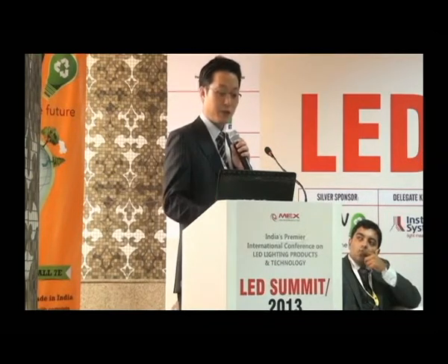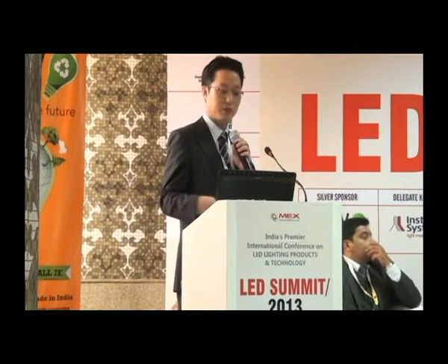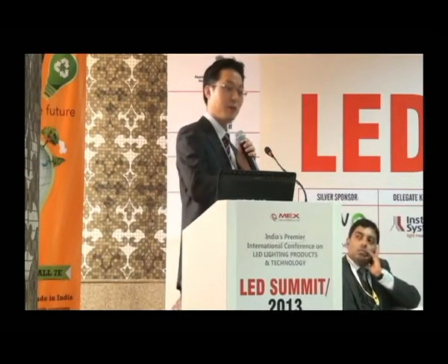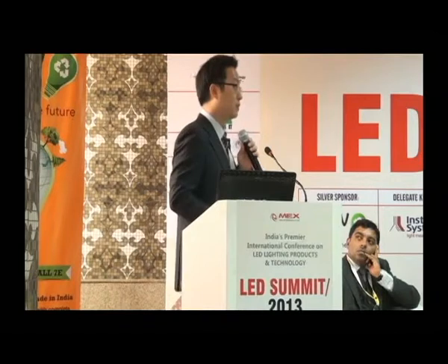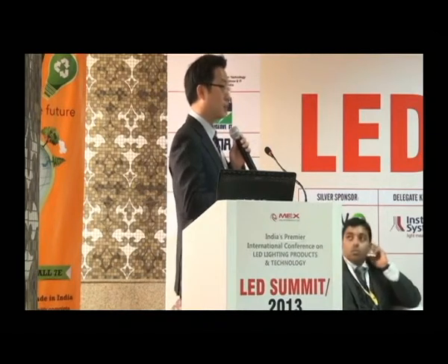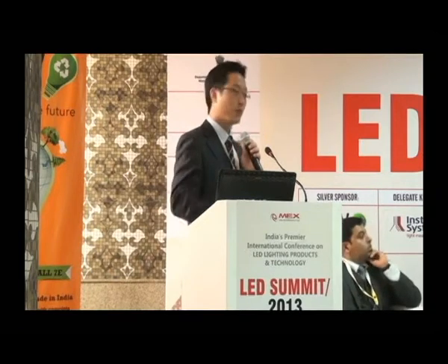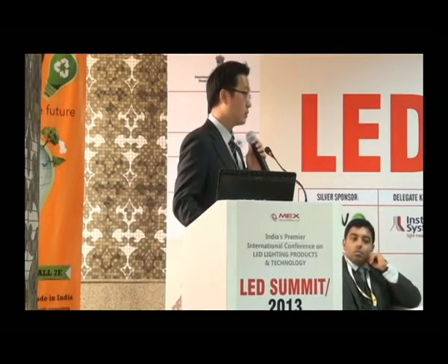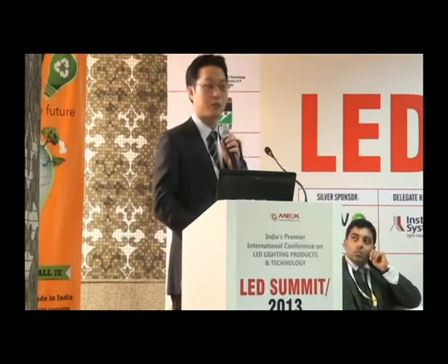If it is exposed to air that has some sulfur gas, the sulfur gas can penetrate into the LED chip, and then it decomposes the silver substrate, and its color changes to brown, and then the color temperature would increase and the light efficiency would also decrease dramatically.